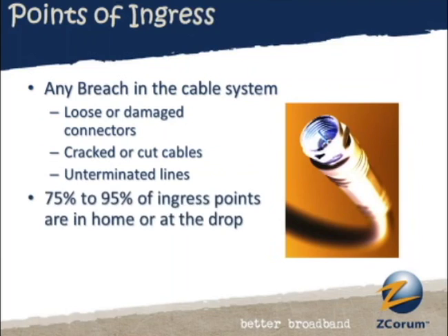Okay. And this is an interesting fact, that anywhere from 75 to 95% of this is either at the home or the drop. And I think the majority of that, maybe 70% of that, is actually in the premise, right? Yeah, I'd be one of the people that would say it's closer to 95 than 75%, and almost all of that is definitely inside the home. That's where we have the most vulnerable cabling. In some cases, it's not even cabling that we put in as the operator; it's cabling that the builder put in.